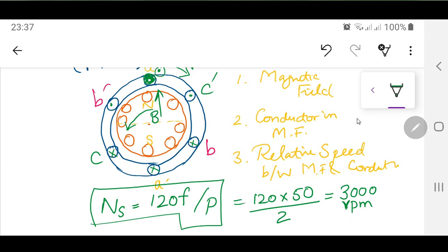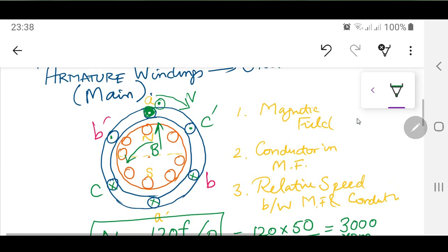Now generally speaking, the DC machines, if you remember, which you did before your midterm, were all having a DC output, but practically there was an AC induced inside them. But by the use of commutators, you rectified them and converted them into a DC output. So if there were many coils arranged in the whole spatial 360 degrees, you were actually rectifying them into DC, and it was a little bit of ripple DC as an output, or in the output you were having a constant averaged out DC available from a DC generator.